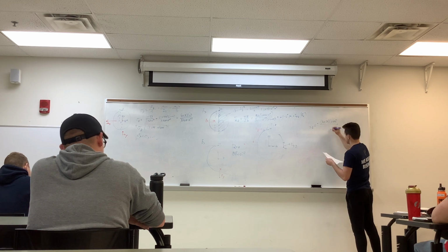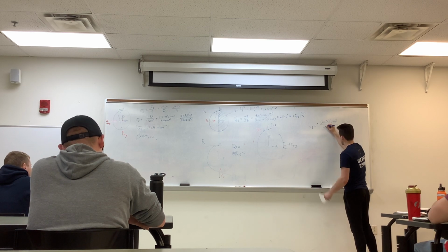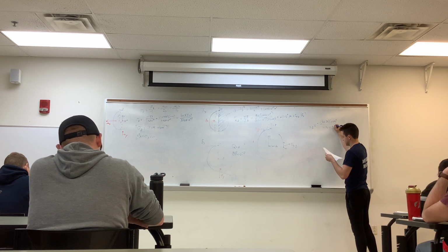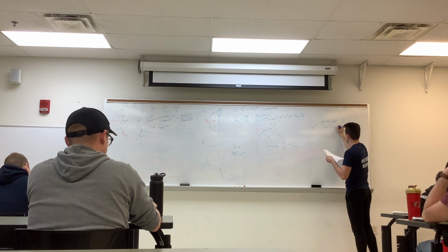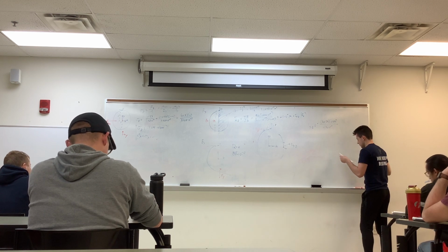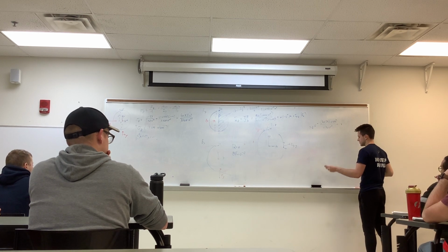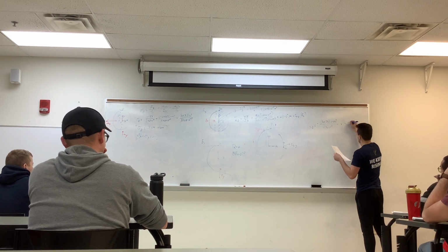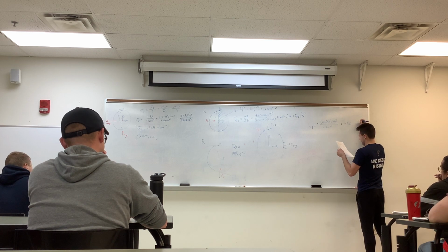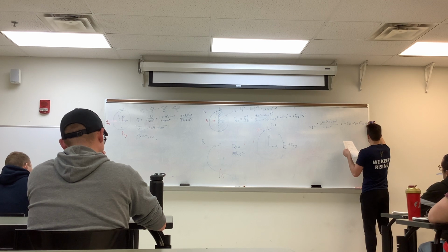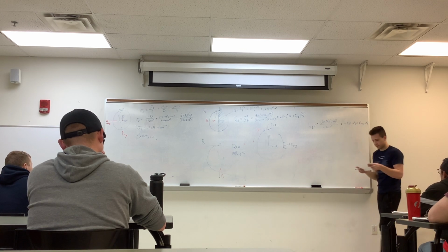All of that over J, which I calculated early on, which was 6.136 times 10 to the negative 7 meters to the fourth. We get this shear stress with regard to torsion to be equal to negative 8.25 times 10 to the fifth Pascal. And again, this is tau xz with regard to our moment at z, or torsional moment.